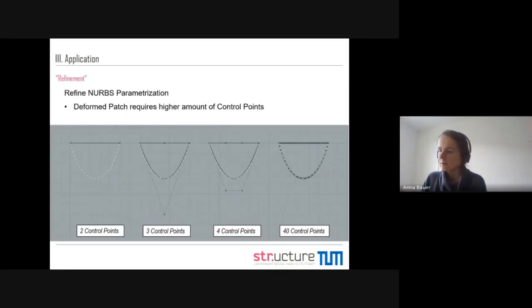And also regarding the refinement, you can draw a lot of nice shapes with very few control points. Here is a not exaggerated example: you can draw a straight line for a cable with 2 points. But if you then want to do analysis under dead weight, it won't deform if you have supports at the ends, because the geometry cannot depict the hanging shape.